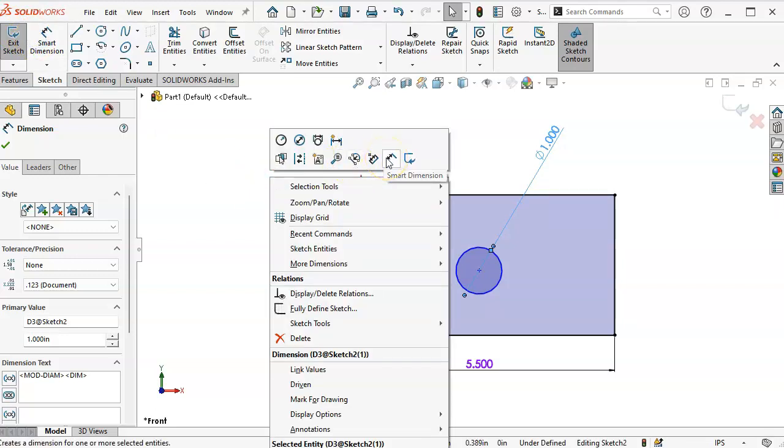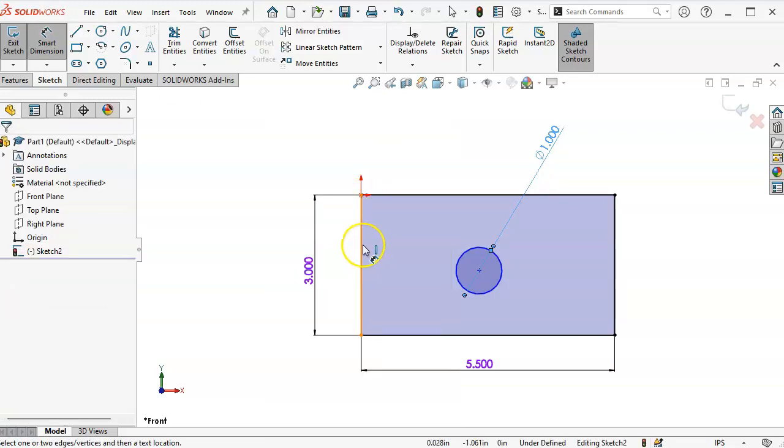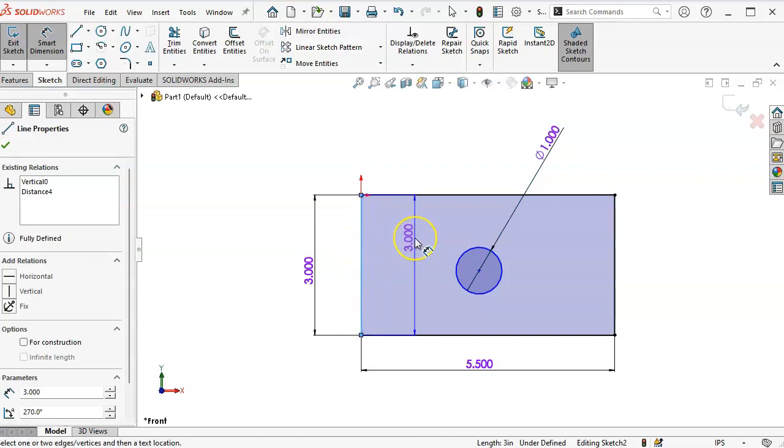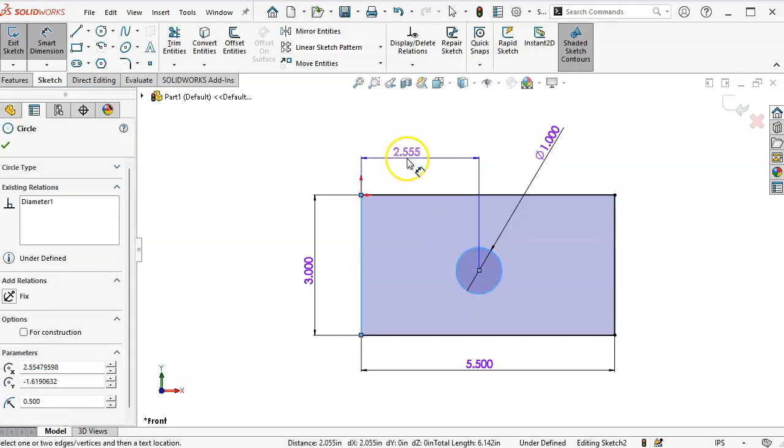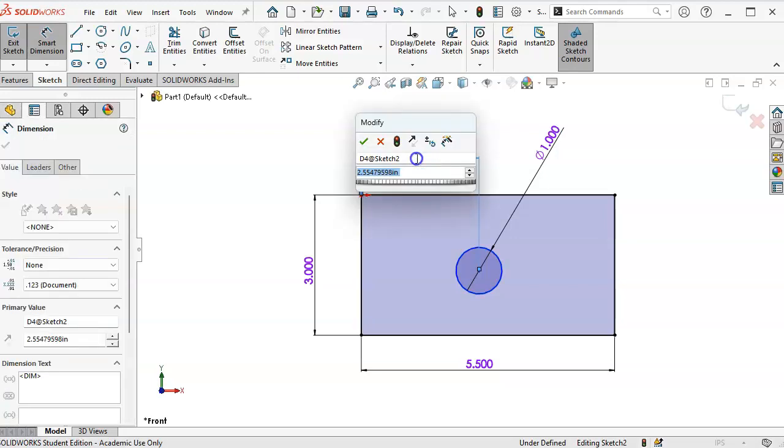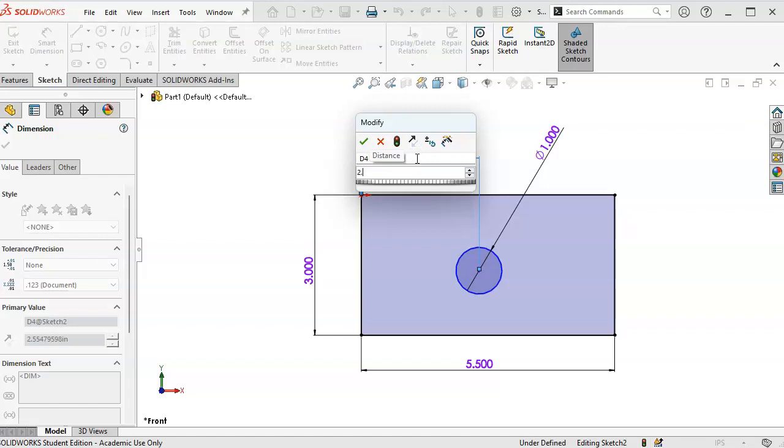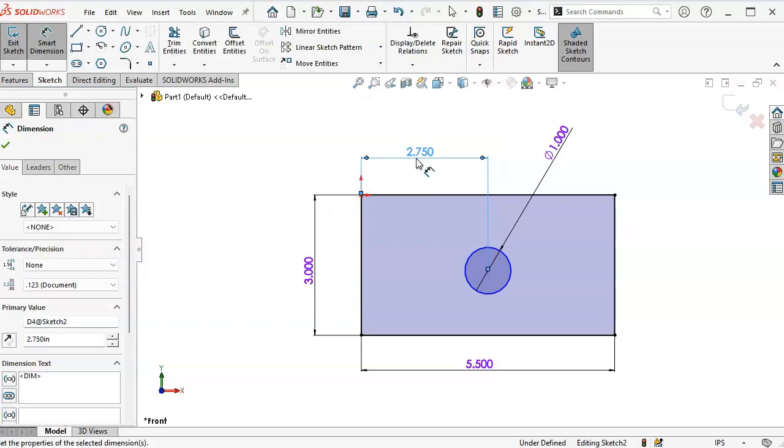And I want to go to the right mouse button, context, and we're going to pick an object, and then preference is going to be the perimeter, the circumference of the circle. And when I click it, it asks me to place the dimension, and we are at 2.75.